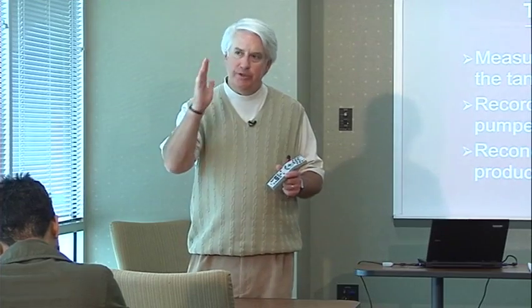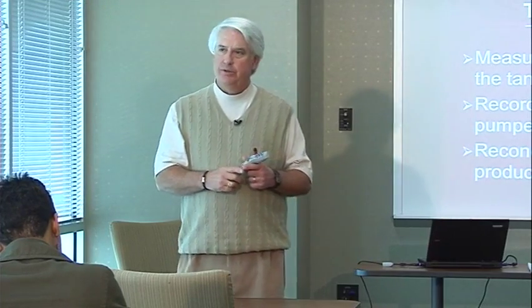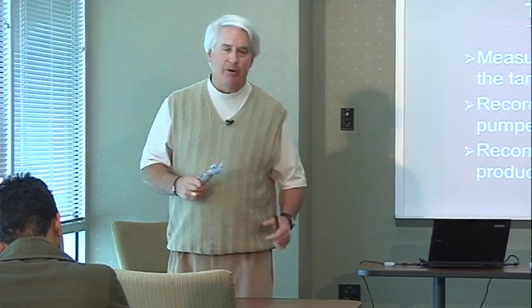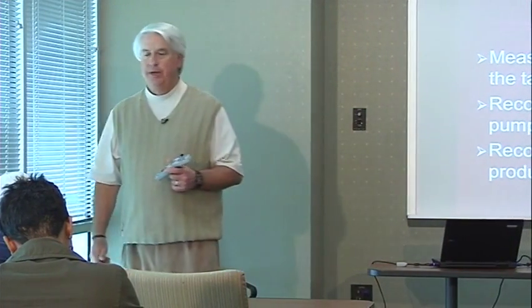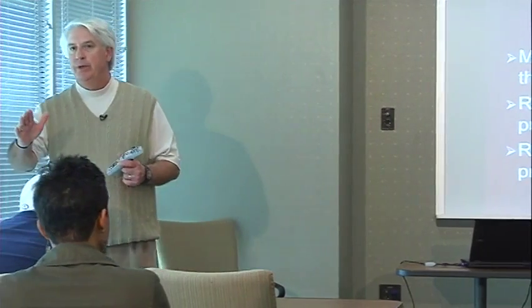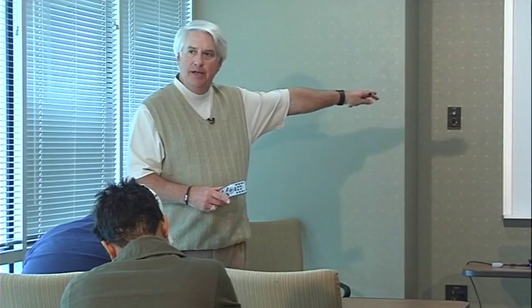You can only do it for 10 years. So just remember that when you see that later on today, when they've got inventory control with tank tightness testing. And I'll just point out too, that tank tightness testing is not a monthly release detection on its own. It has to be in conjunction with inventory control or manual tank gauging. It's not a release detection on its own.